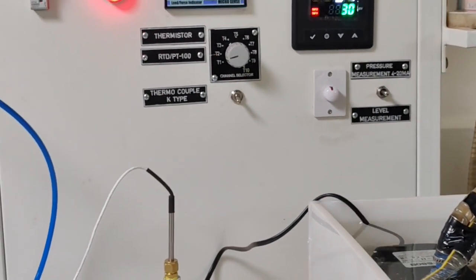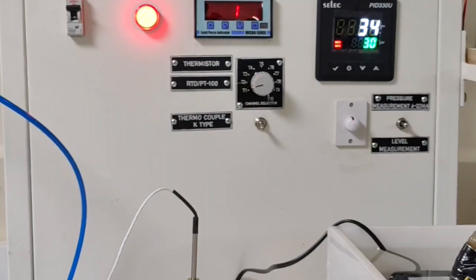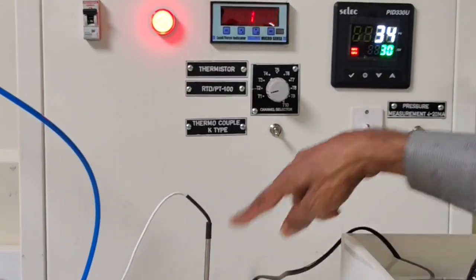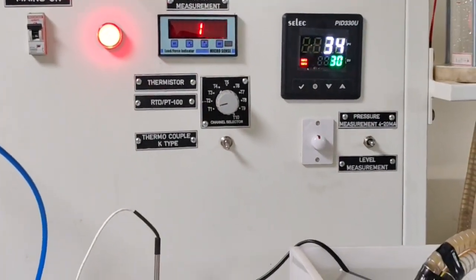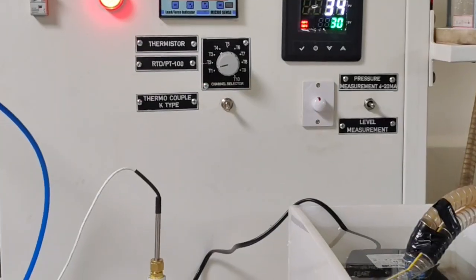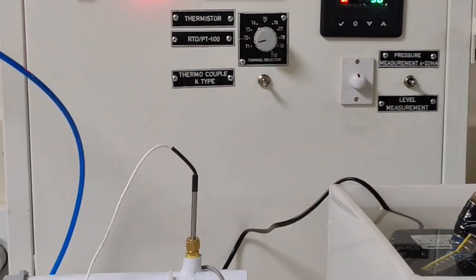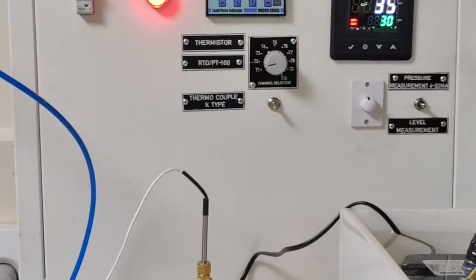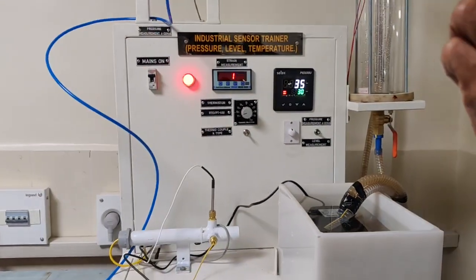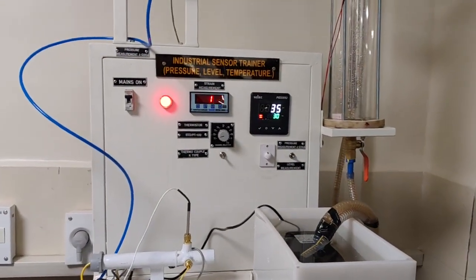I will show you the chart also. I have the chart. You can give it. So now it is raising, it is heating. Now it is raising temperature. Like that, 3 different you can study. Now we are studying with K. Go up to 50, 40, 60 degree, whatever you want. Accordingly, what is the millivoltage is coming, that has to be read.